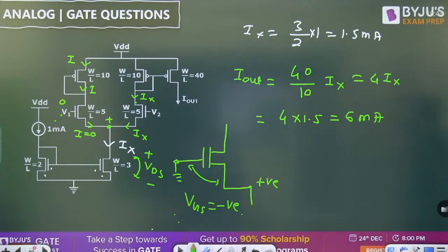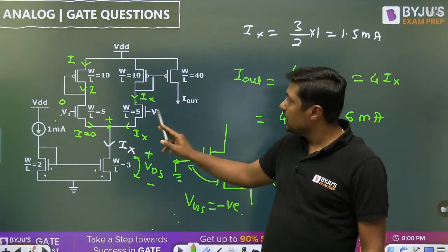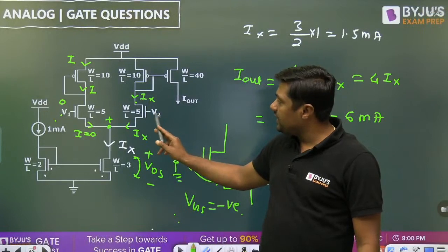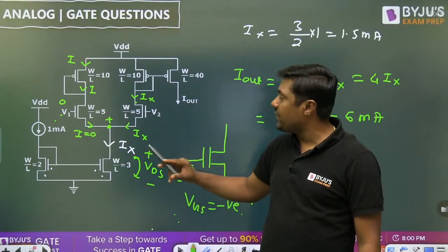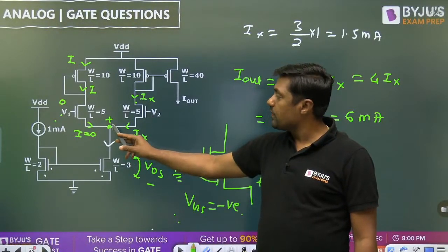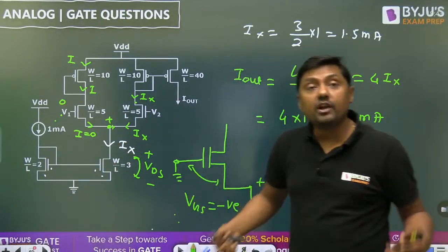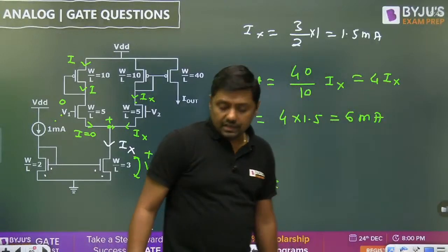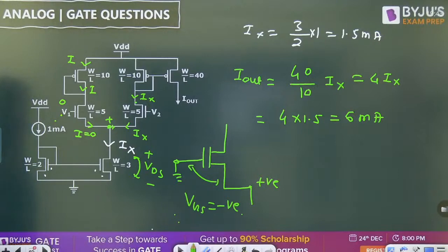This is V1 is actually because of that 0 value and because of this VDD. For example, it is VDD is given. Try to understand this concept. If this is the VDD is given, my dear, there will be the drop across a drop of what? For example, VTH, and VDD is 5 volt. 5 minus 1. So what is the voltage at this point? 4 volt. 0 minus 4. So what is the voltage at this point? Minus 4 volt. Definitely it is in cutoff. Okay. In this way we can find the value.